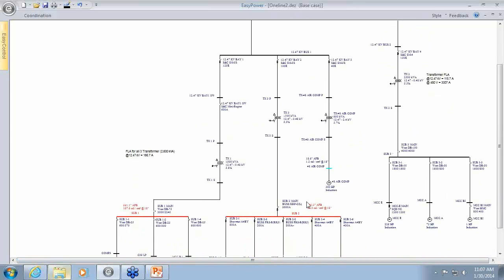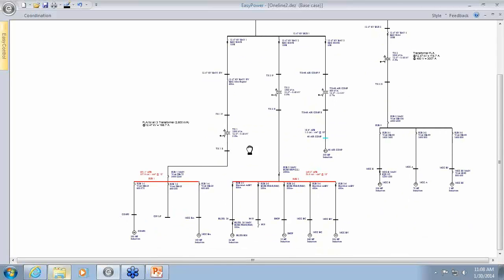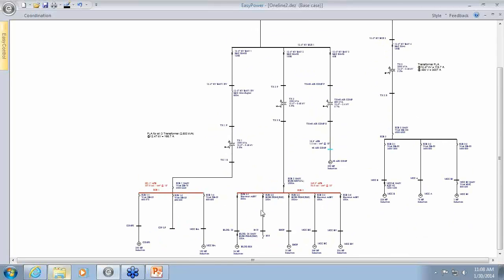So this 54.6 passed through the whole switchgear, and so if they needed to operate these or get into the switchgear, they needed a way to get it below 40 calories. So their choice was to enable a maintenance mode setting.